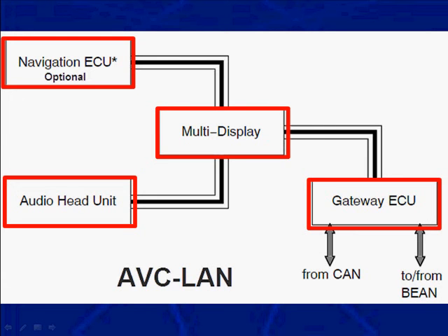And you think, why would an audio have to talk to a hybrid controller on the CAN circuit? Well, the CAN circuit is part of the hybrid controller, and the hybrid controller talks and tells the multi-display what's happening in the hybrid system. Are we on ICE only? Are we on ICE and electric motor?